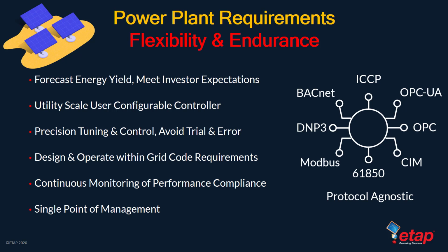Developers who are using non-model driven tools are usually not aware of or do not consider several additional losses, and therefore are not calculating a long-term yield prediction over the lifetime of the project with a higher uncertainty analysis. Typically, an investor will look for a higher level of confidence in the energy yield prediction, typically expressed as the P90 value, or the annual energy yield prediction that will be exceeded with 90% probability. This is only possible by utilizing a model-driven power system analysis solution.